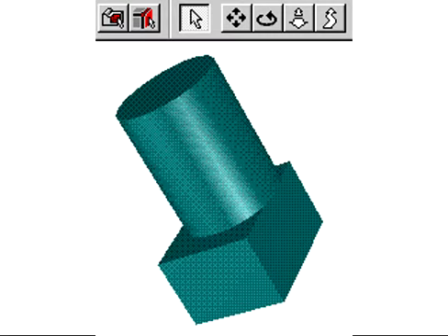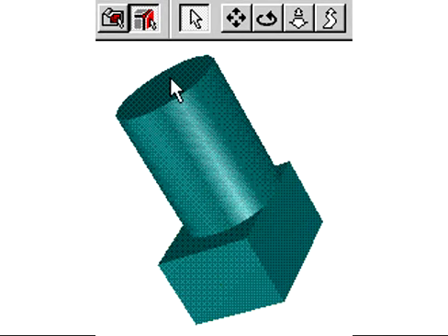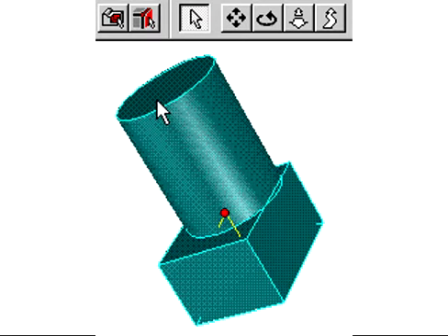If you want to work with a series of shapes or edges, use the selection tools. Click the Edit IntelliShapes tool to work with shapes. Whenever you click on a model, you select a shape. Click the Edit Surfaces tool if you want to work with a series of surfaces, edges, or vertices. Deselect both tools to work with the entire model.